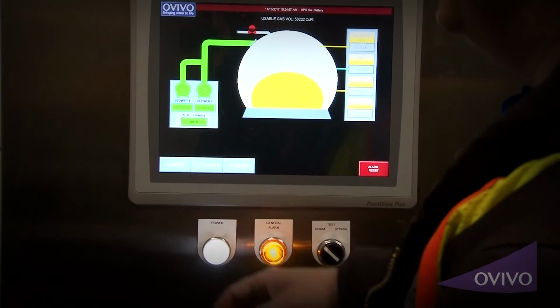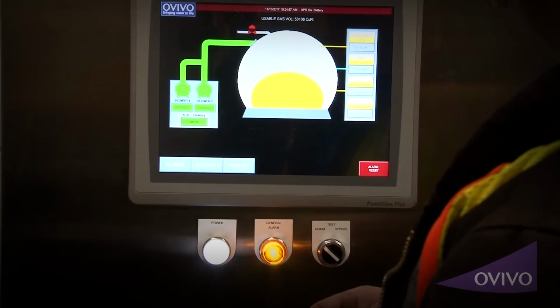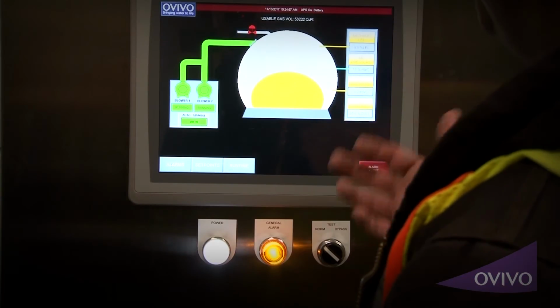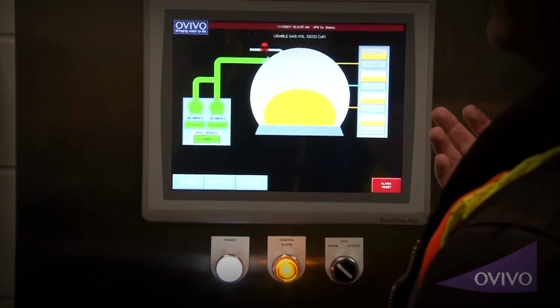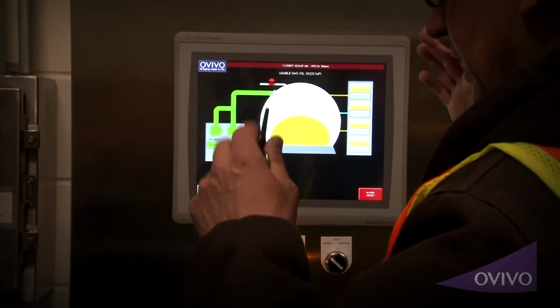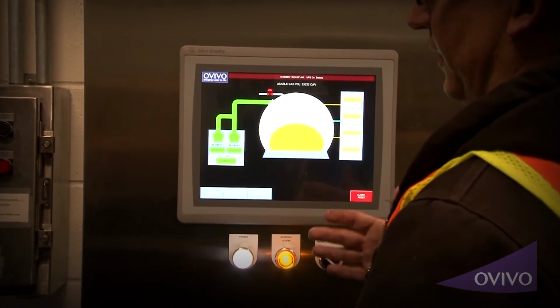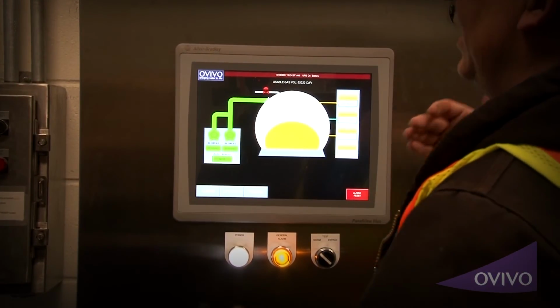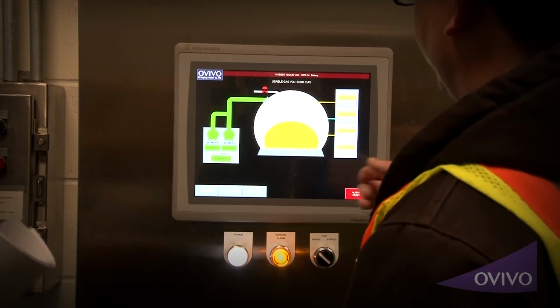Well, if you're making gases, you're probably never going to see two blowers come on. No, you might. The only time you'll see both blowers come on is if you're sucking out the gas faster than you're taking fluid out of the tank, and all of that would affect the pressure. If it hit 2 inches of water column, then it would set it off. But for the most part, you wouldn't have to worry about it.